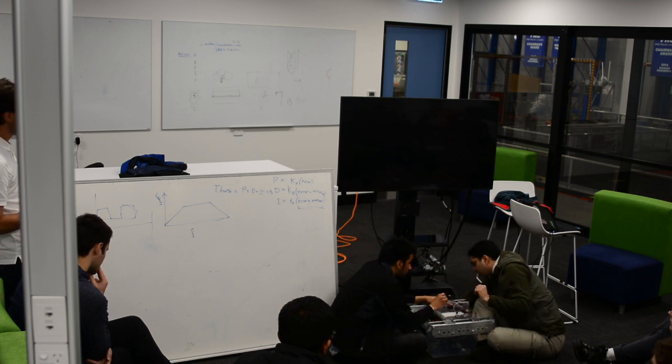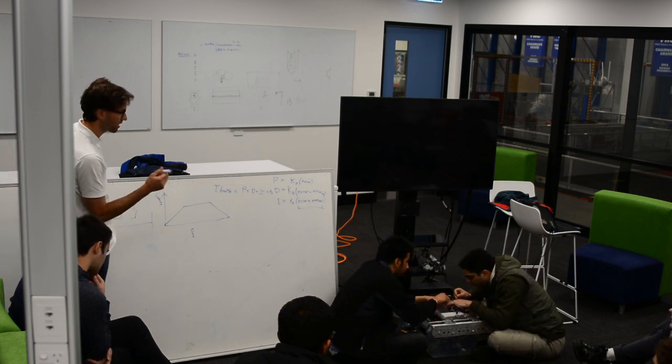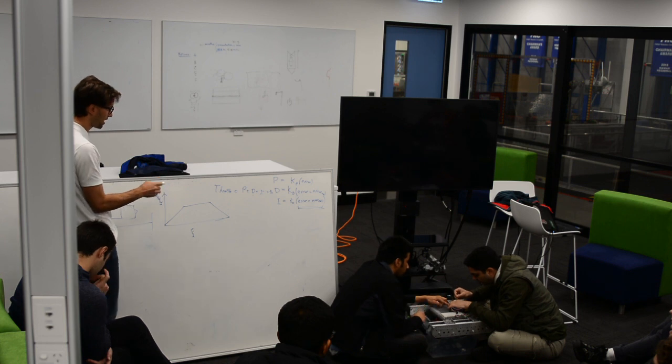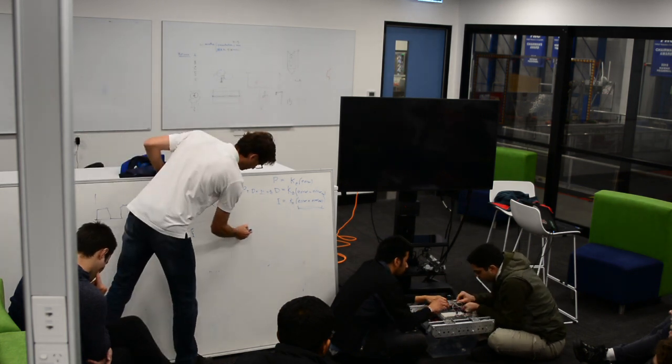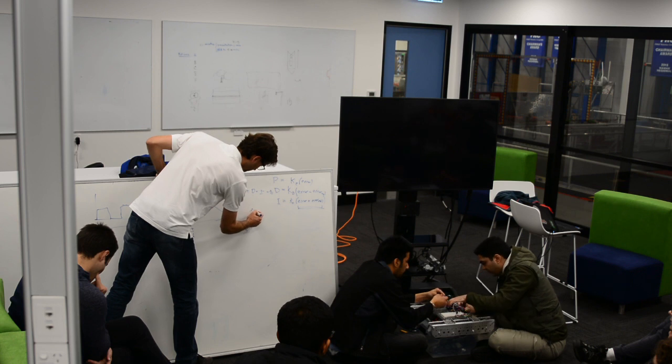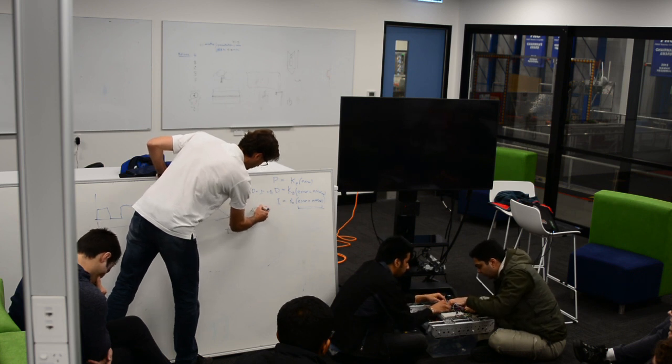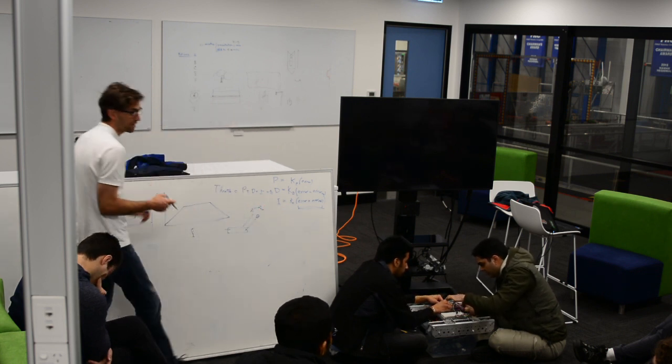The other thing that the Arduino libraries will do, and I don't know if you should do it though, is you can send, we'll remember we had that motor, and it had an A and a B, and we sent this one to an interrupt. You can also send that B to an interrupt, too.